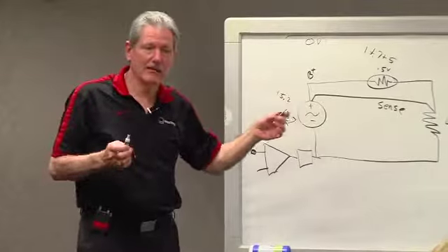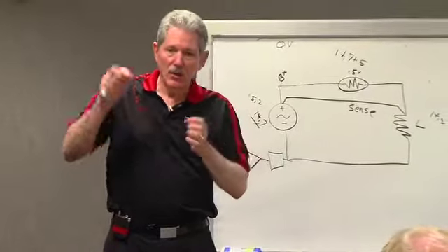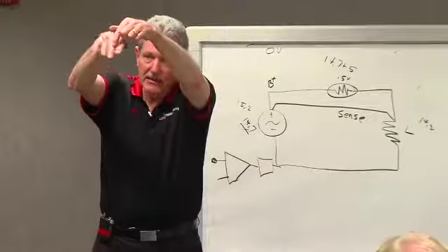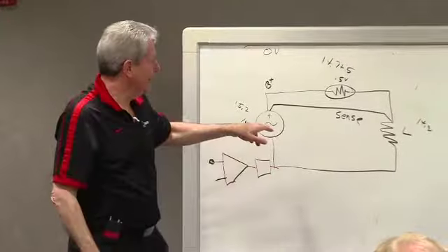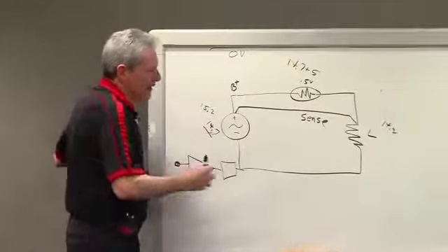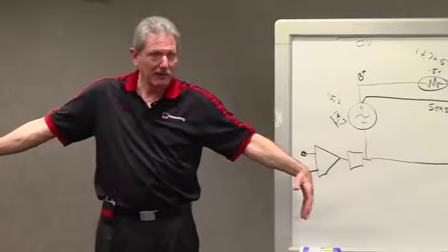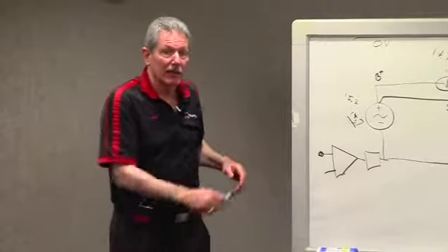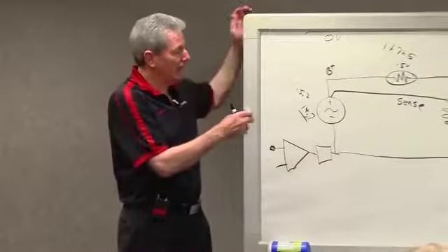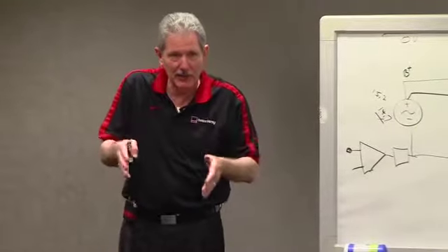A Kelvin connection is a 4-wire connection, where you force and sense, force and sense. This is kind of a half Kelvin because the ground generally has less resistance because it's the vehicle body. So you don't have much drop across that. So that's the reason why you have this on heavy duty, because the battery is seldom in the engine compartment.